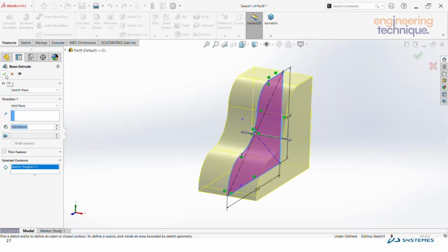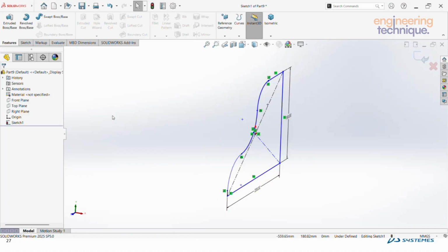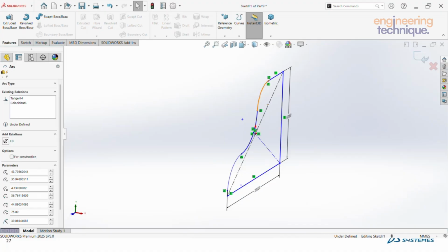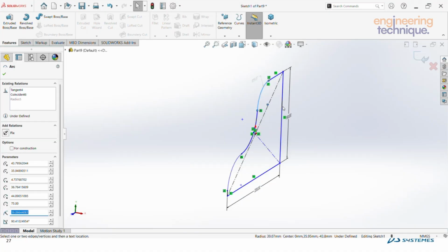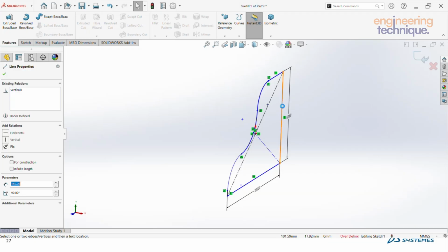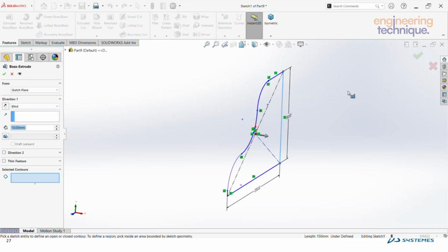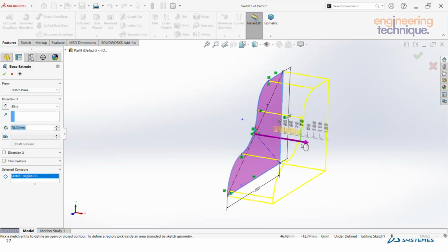My specific suggestion to all the designers is to use the direction one option. It is very helpful, and it will create the geometry nearer to our origin point. It will be helpful for creating any further assembly point or anything. It will give you the best result without creating multiple reference geometries. It only works with the existing geometries and directly provides you the best options.